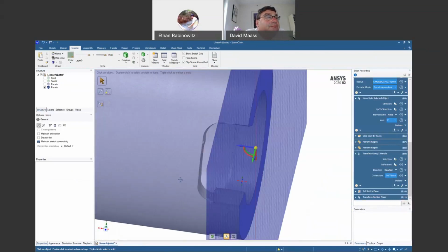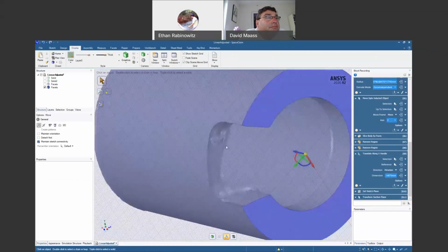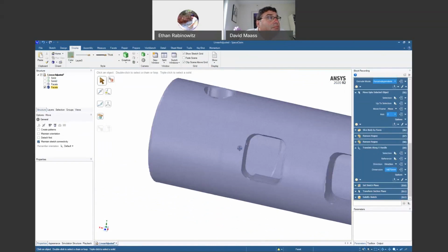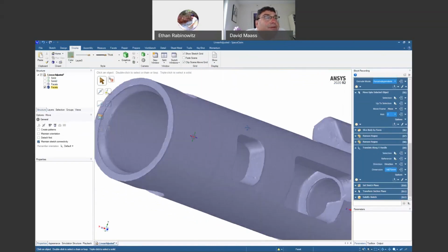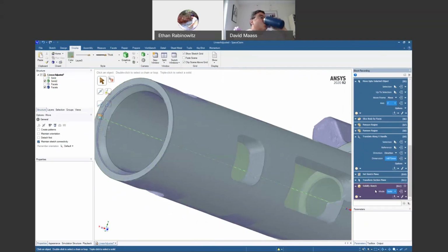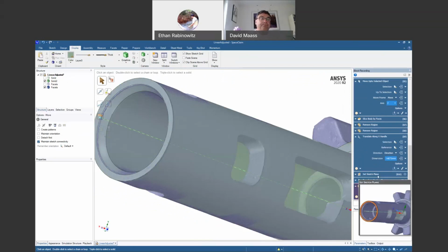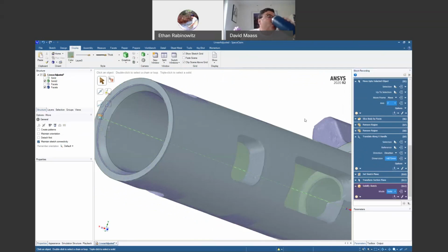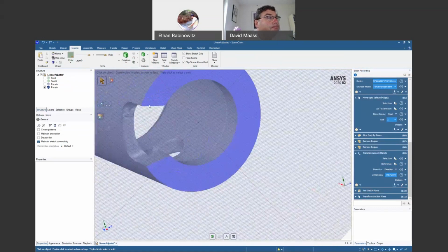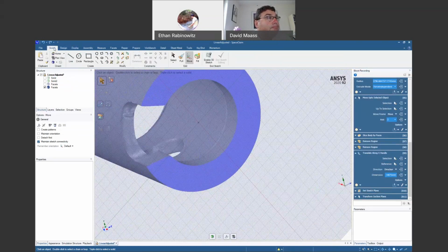Okay, so new game plan, which is actually going to be pretty easy here. These are at a weird angle, but I'm pretty sure that these walls here are just parallel to these front faces. I would think they looked that way. Yep. All right, so let's do this. Let me undo, because as the block recording is on here, it's recording each of the things. So I'll go back to where I want to be. Essentially what we'll do now is sketch a line across here, cap it off, and then cut either way with it. This should be pretty easy to do.